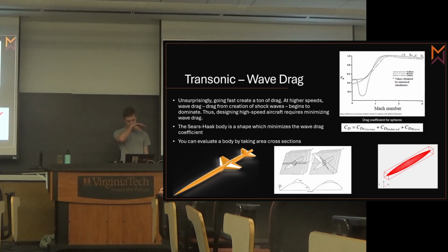I also didn't get a picture in here, because I just remembered it now, but there was a pretty famous aircraft that looked the exact same. They could only get up to Mach 0.95, and then they went back and followed this area rule. They just barely changed the geometry in a couple places to better fit that, and then it can go past Mach 1. So it works. Oh, and I didn't mention the CD increase.